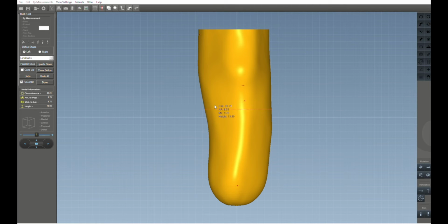Sorry. So I select a single plane. I can select the plane. I go over here and I say trim top, and it just cuts off a piece of the top. Cutting off the top or the bottom if necessary allows us to eliminate unnecessary parts of the model, which results in us using less material when we fabricate. So it's quite an important function, especially in today's age of printing. Sending a large model just wastes material.